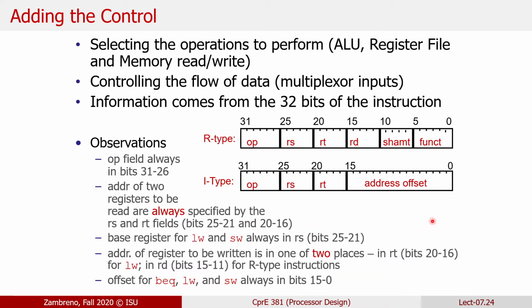So we've covered a little bit in earlier lectures about what it would mean to add that control to our diagram, right? Up to this point, the control signals are just kind of floating in there and connecting to muxes. For your existing implementation, we are just manually setting those control signals. We're pretending to be those instructions. If we know it's a load word, we're setting the appropriate muxes and ALU control, and we're doing all the things that would correspond to a load word.